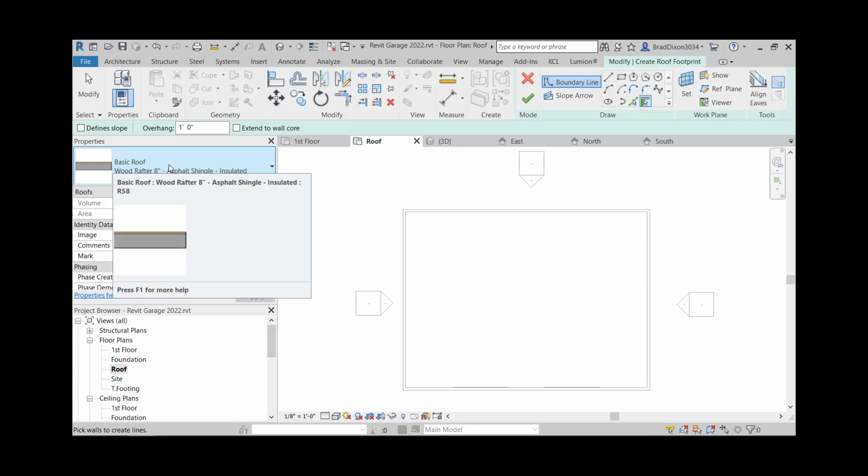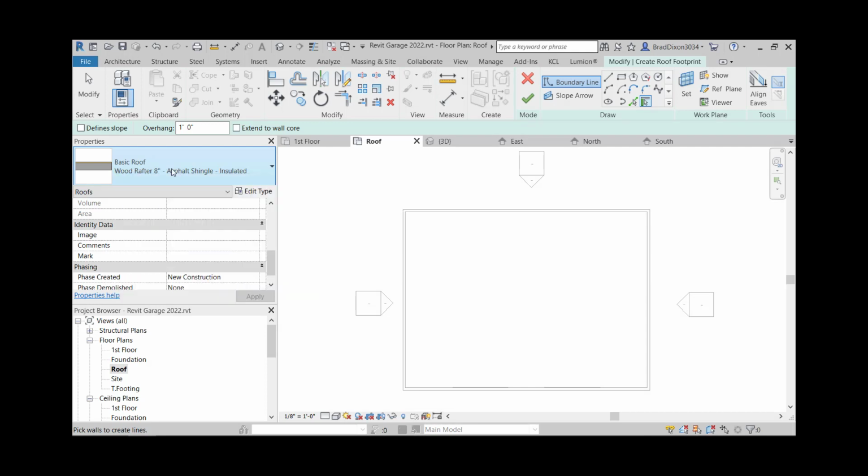So we're not actually going to use rafters, we're going to use trusses, and they're engineered to use smaller components of wood. Very often you can get away with a bottom chord, which would be the part that stretches on the bottom of the truss, not the angled part. You can use a 2x4, and then the top chord you can use 2x4 a lot of times with this kind of span.